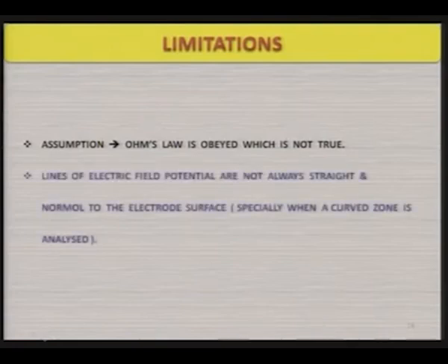Now, there are certain limitations of this particular method. It assumes that Ohm's law is obeyed, which is really not true, especially when the inter-electrode gap is not plane parallel, as Ohm's law holds true only in plane parallel electrode machining. Lines of electric field potential are not always straight and normal to the electrode surface, especially when a curved zone is analyzed.